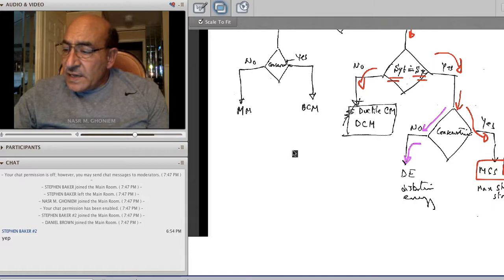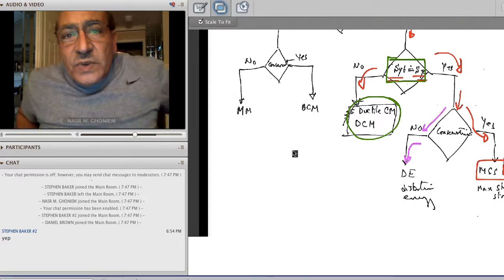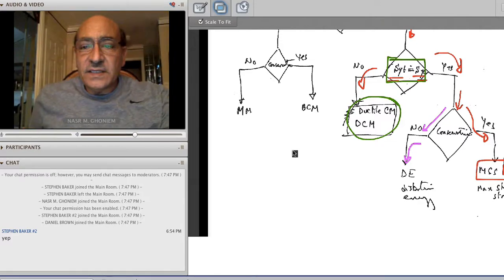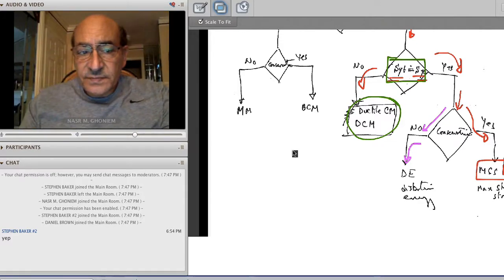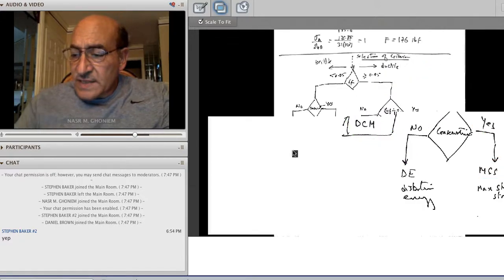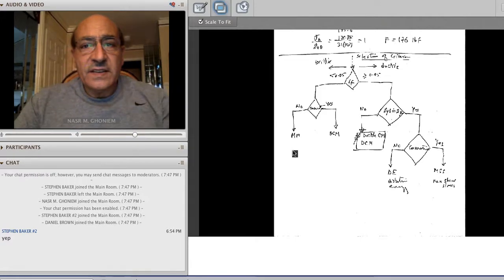And then again, if the yield in tension is not equal to the yield in compression, then I use the ductile Mohr, where instead of ultimate strength everything is just the yield in this case. So that is what I have in terms of a review, and I wanted to see if you have any questions before we talk about some other things.